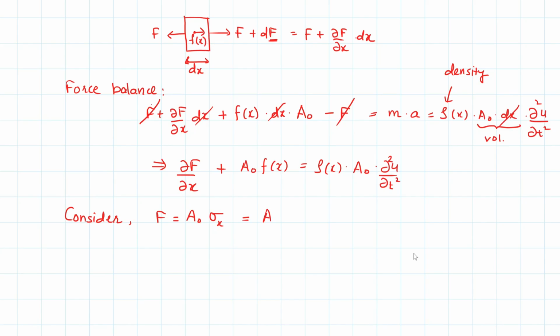Now from our constitutive relation we can write sigma as Young's modulus times the strain, which I can write as the derivative of u with respect to x. Okay, now substitute this back into the above equation.